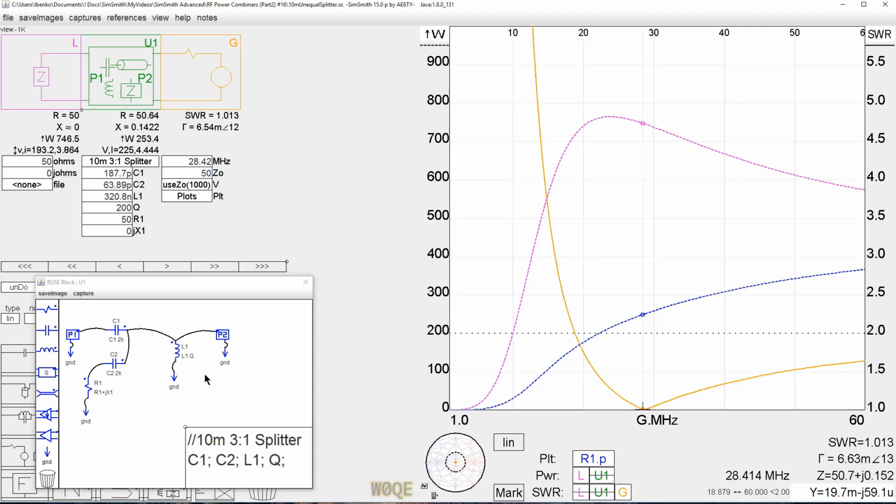And that's exactly what I told the guy to do. He had told me he had a whole bunch of tuners floating around, and he put a coax connector in the back of it, wired to here, plugged that into his transmitter, plugged here into his dipole, and this point into his Yagi, and he went to it. Now, for him to be able to do this, he needed to put a power meter here, a power meter here, and he needed to look at SWR back here. But I gave him some starting points on the values, and he said he got it fine.